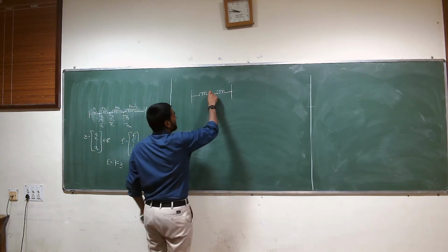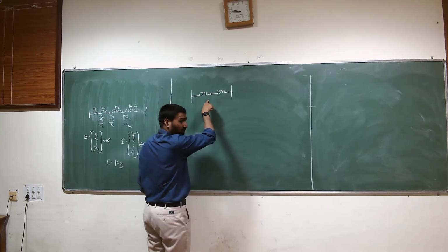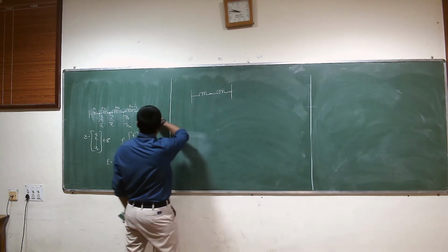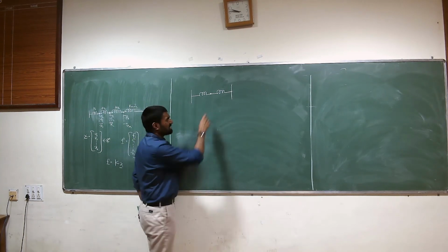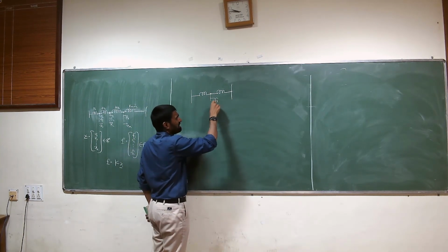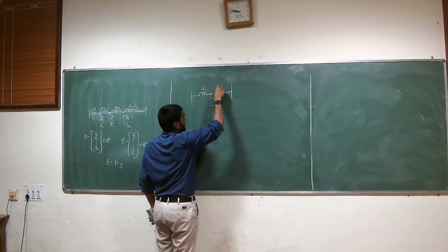Okay. If you have the 2-spring problem, how many forces and displacements would we have for a problem like this? Assuming this n is 2, n is 1 here. There is only one force, F1, and there is only one displacement that we are interested in. This has a spring constant K1, K2.